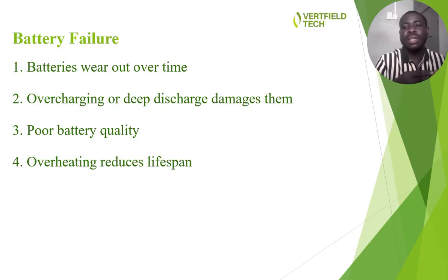And all the days of the life of this solar generator, the battery systems are being drained and recharged, which is a very wrong method. It is not good, it is not advisable for you to drain your batteries completely. Even if you step aside the solar generator issues we're discussing here, on a normal basis, even for your normal solar system in your facilities, you are not expected to drain it more than the assigned DODs.